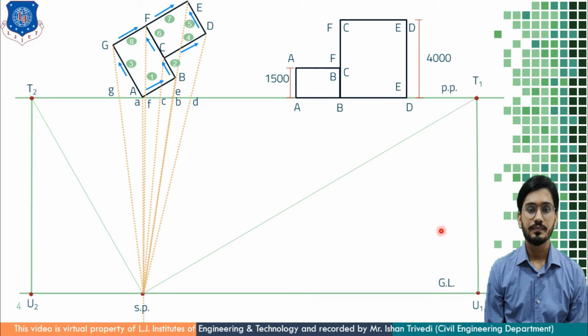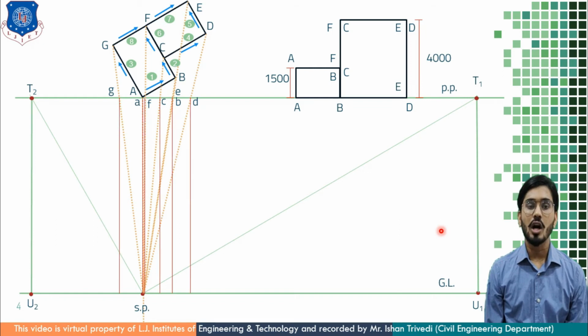Now I am going to draw a parallel line. This intercept which I am getting from the picture plane, I am transferring to the ground line and making a perpendicular line. So here is the perpendicular line. As in the previous case, you can see this was only drawn for the reference of the intercept, so I am eliminating those lines so you can have a better visualization for your drawing example.